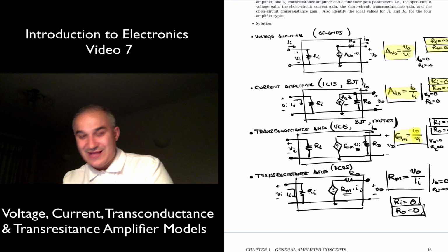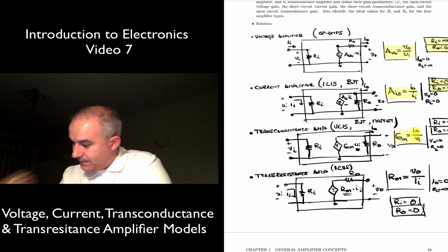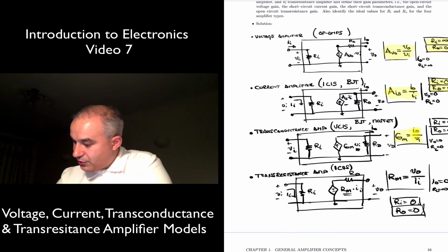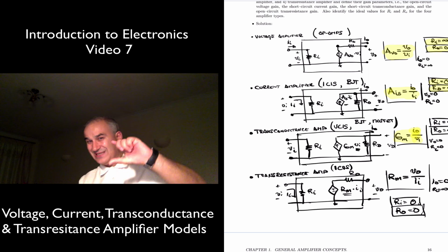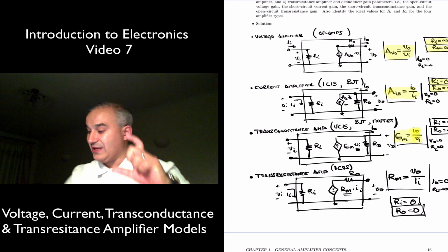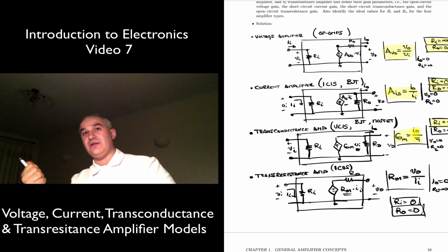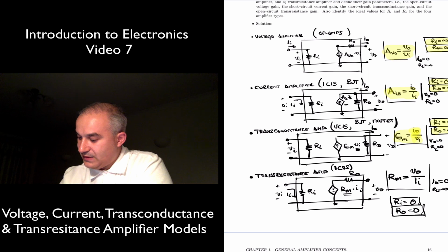That's the transconductance, and that's the transconductance in short circuit conditions, because you want to do this when the output voltage is equal to 0. Ideally, what do you want in a transconductance amplifier? You're sensing an input voltage, right? So you want an input impedance that is infinity, and you're producing an output current, so you want the output impedance to be infinity.